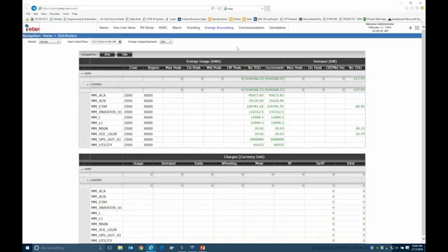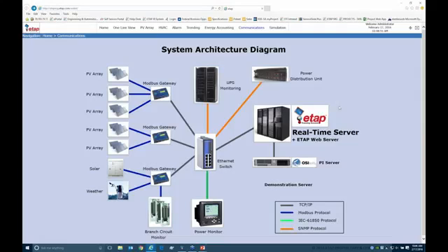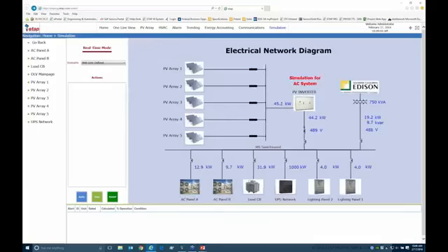Other things you can do here is energy accounting, and that's how I actually got my kilowatt hour numbers. You can also see the communication diagram to make sure everything's operating correctly, and we're using various protocols here like Modbus, 61850, and SNMP, amongst others. And here's the neat part. I can also do my simulation from right here. So here's how my system is running right now.